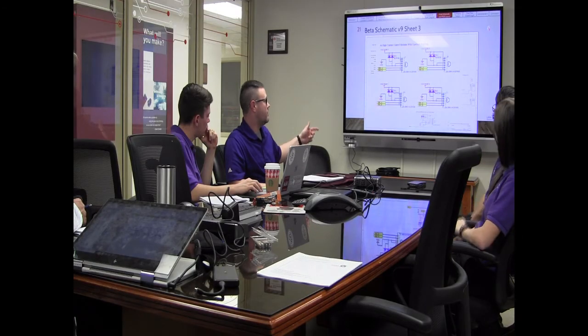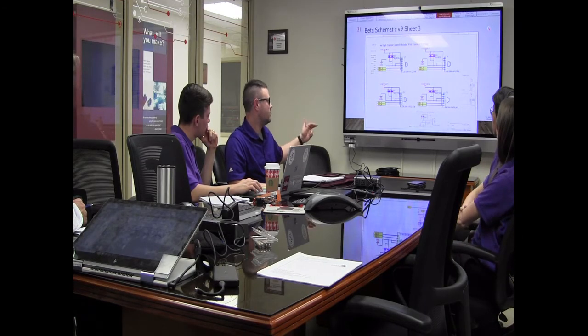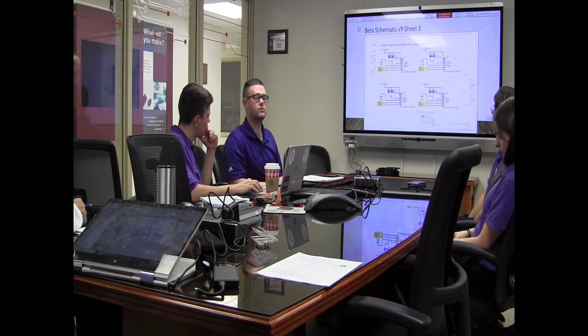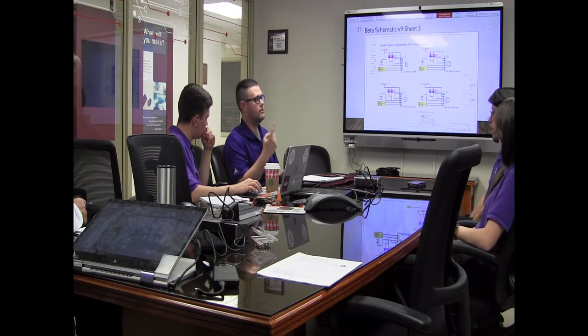Channel A is on 5, H bridge number 0, channel B is on 6, so that way you can have full control of the motor. Those have a 12 volt input and they use a little bit internally, and we were seeing at full 100% duty cycle right around 10.7 or so volts at the load.